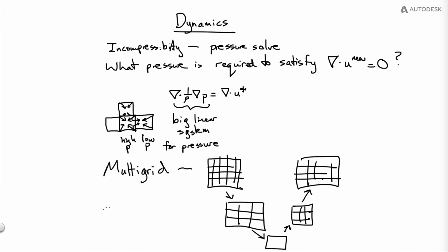So instead, we use something called iterated orthogonal projection. So we do a multigrid pass to make the fluid respect volume conservation, and then we make sure that it also respects solid boundaries, so any colliders you have in the flow. You don't want the fluid to go through the collider. If I've got what looks like a sack of potatoes here, I want instead to fix those velocities to go around my sack of potatoes.